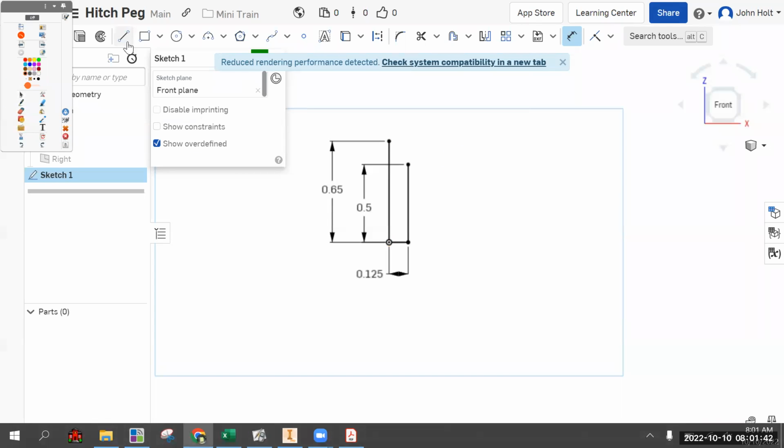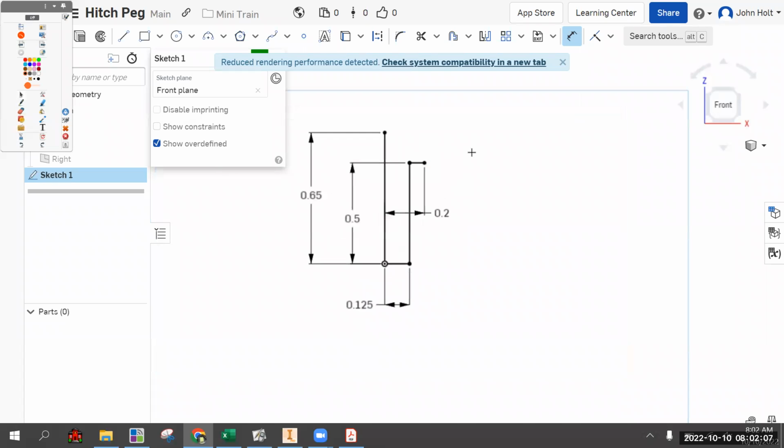And that's what we're going to actually do. So from here, let's get a new line, snap it to the end of here, make sure it snaps to horizontal, and get the dimension tool. And what is our dimension? Our dimension is the distance from our center axis to the end point of this line. You can see how it's turning yellow. We can just put it here out of the way, and 0.4 divided by 2 is 0.2. And that gives us our line.